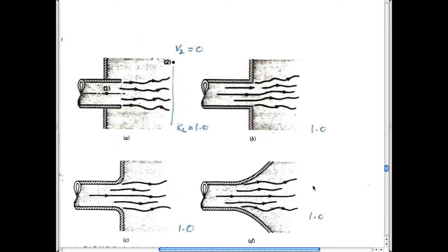Also, we talked about this idea of friction, right? You're doing work against something. If I push my bag to the right, I've generated friction, I've lost energy. If I pull it back to its starting point, I net lose more energy to get it back to that same point. So if you start at zero velocity, accelerate along a pipe, and then flow into a big tank, again at zero velocity, then you don't necessarily recover that energy. You have losses in that case, not really due to friction, but by the fact that you've accelerated something and then decelerated it, and you've lost energy as a function of changes in acceleration.